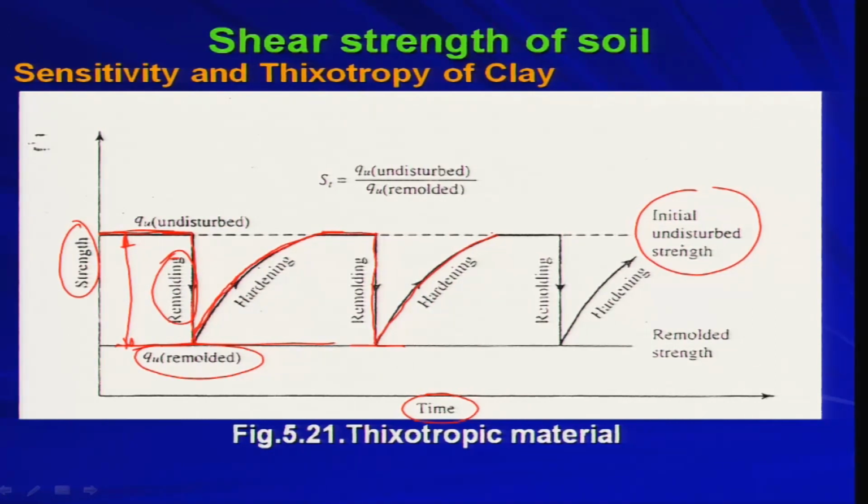That is why, if you disturb the soil, after certain time the soil will regain its strength. This is known as complete thixotropy. That means whatever strength the soil loses, the same amount it regains after a certain time.